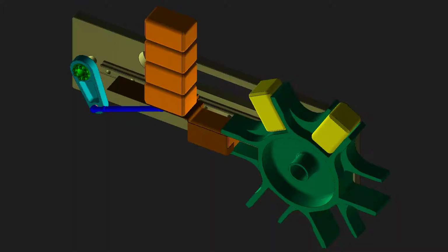So we can start by writing down the kinematic motion constraints. These are requirements that must be satisfied for the machine to work. I use the word kinematic because they define the condition under which the machine will operate, assuming all mechanisms and machine parts are infinitely stiff, strong, and have available a limitless amount of power to drive them. Another way of thinking is to define constraints without regard to power, forces, and torques.